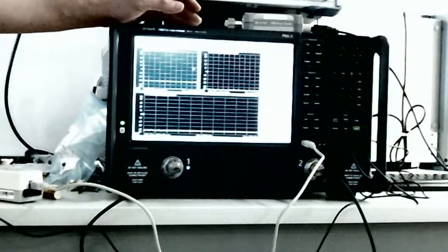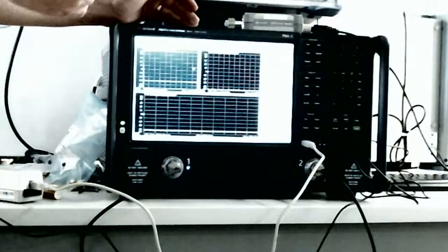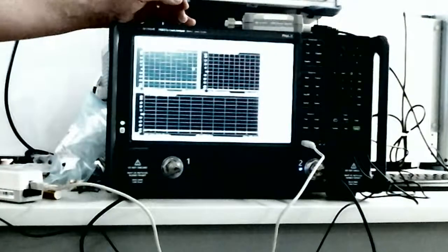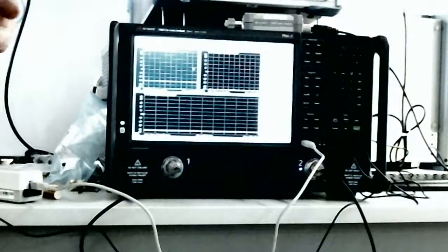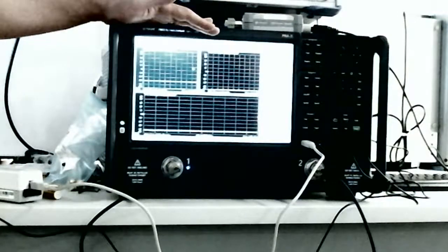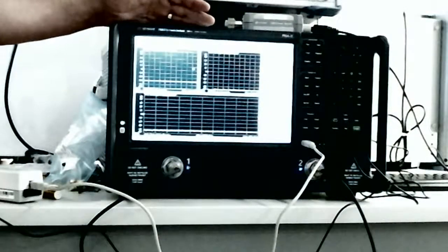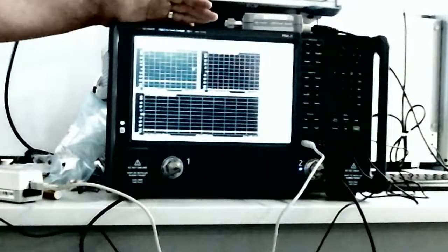At minus 20, if you have minus 40 dB of reflection, and you come back, you're already at minus 60, and then you go through a coupler to get into the receiver. Now you're at minus 70, so you're getting into kind of the noise floor of the measurement, right? In terms of the capability of the measurement. Remember what I said about the best corrected match that we can expect, right? It was around 43, sometimes 47.